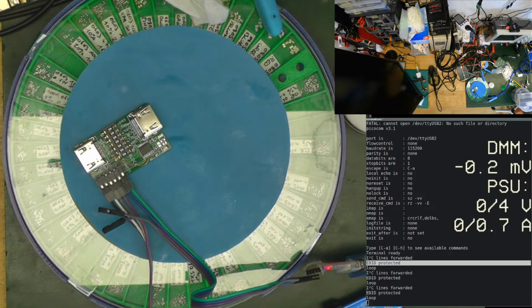Yes, I can do that. I can initialize the pull-ups and pull them up. Once they're forwarded, I can still pull them down. Would it be an issue? No, because it adds just a 1K, and there's already a 1K. It's not too much of an issue. Yeah, let's fix that. But I need to define which one is which.